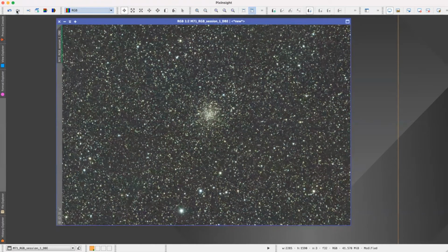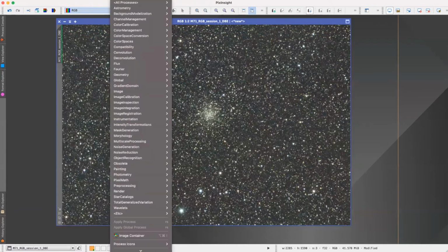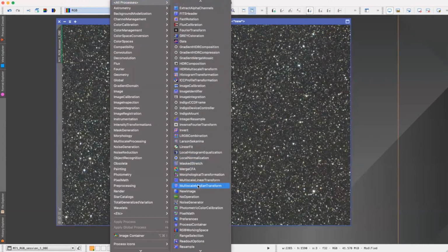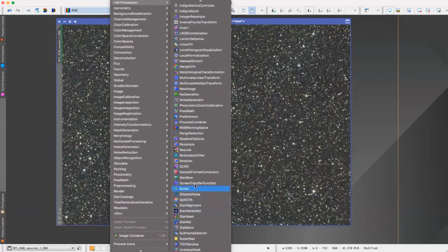Background is certainly clearer, and it's definitely taking away a green slant or hue against the object, M71 itself. So hopefully that shows that photometric calibration has certainly done its thing. So just to finish off the color calibration, what I normally run here is the DCNR process. So just load that process up, DCNR.